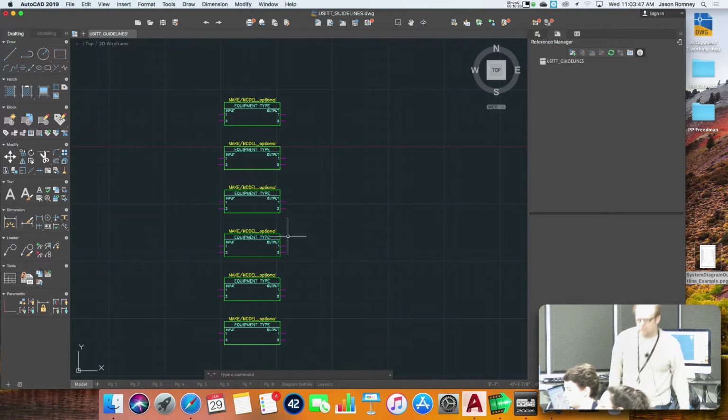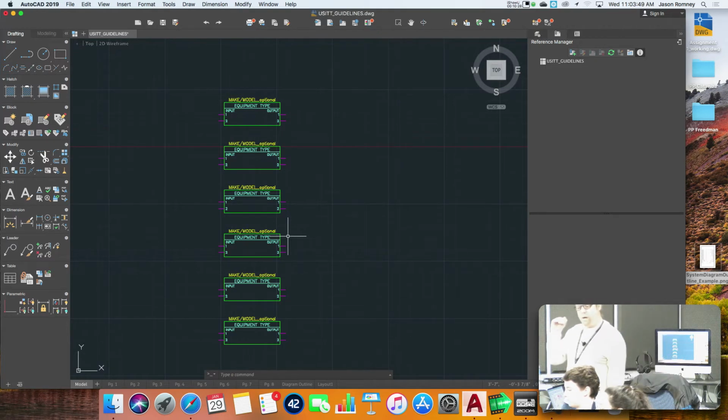So try and do that. So this is where, remember I said usually your origin point for copy is the thing you're copying. But there's an example where you might use an origin that is outside of the object that you're copying, because you can use that spacing that exists between the two objects already to create appropriate spacing with everything else. Okay?